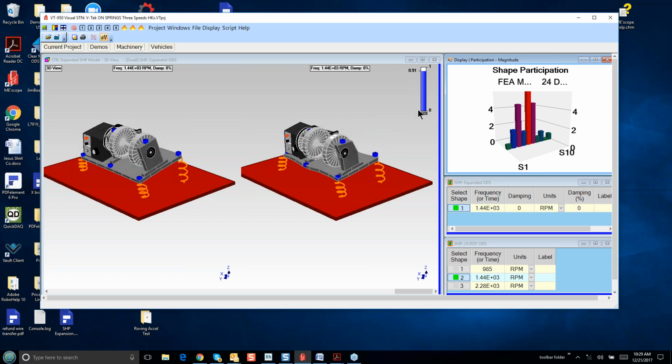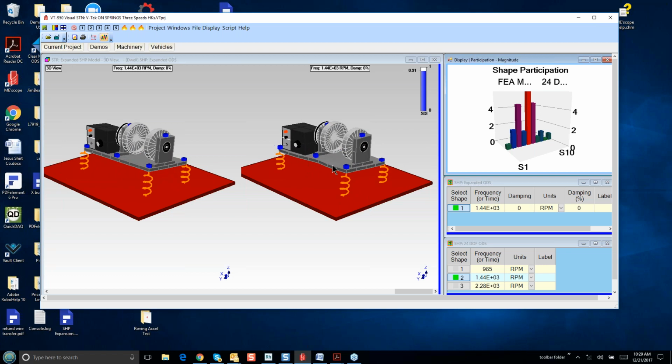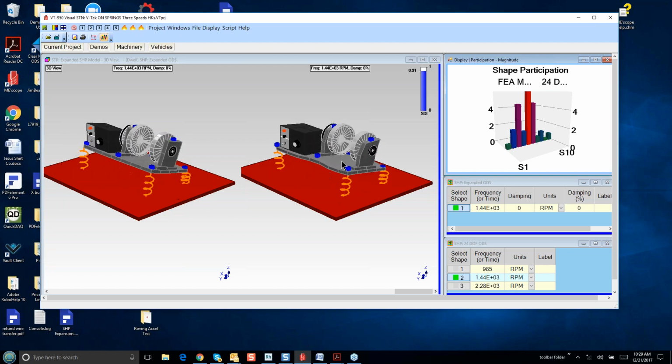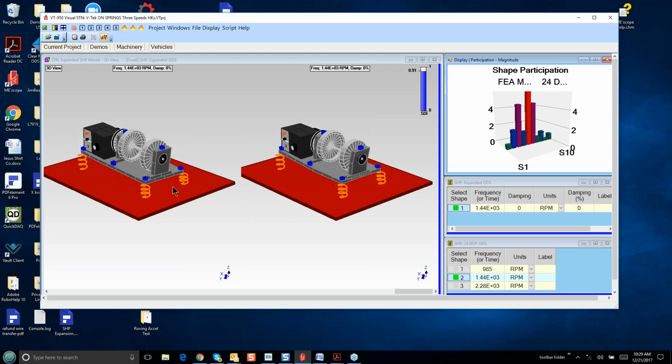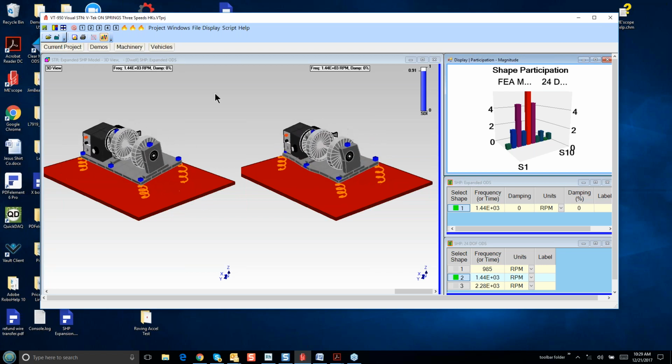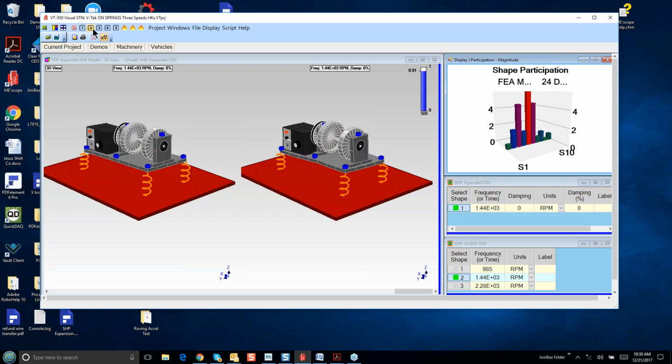And the SDI says they're 91%. So the curve fit is even doing a better job at this higher frequency. You can see the linear interpolation over here where the geometric is not real good, but over here we got very nice motion because we've got a very smooth ODS there. Let me go to the next frequency.